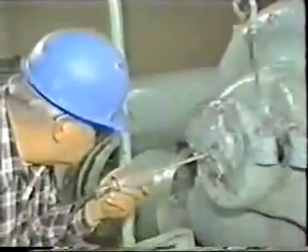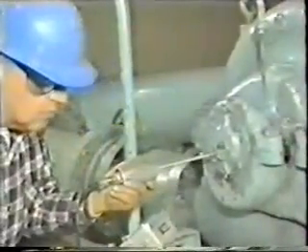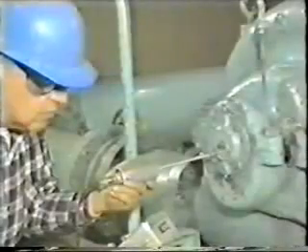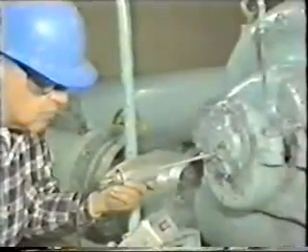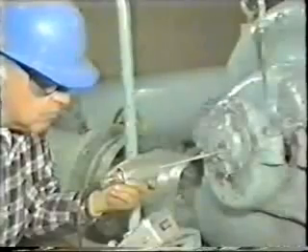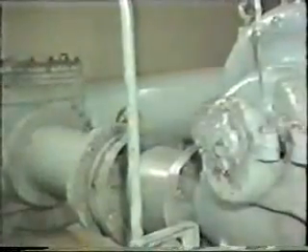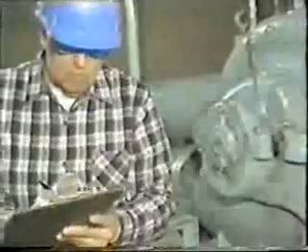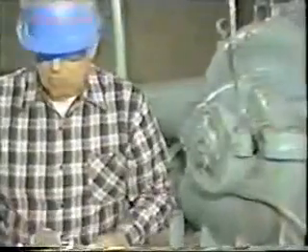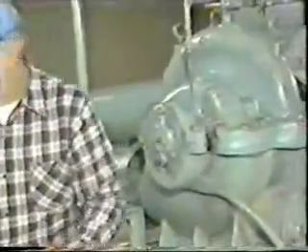When the probe is placed on the end of the shaft or bearing housing, the meter measures axial vibrations. Any excessive vibration readings on this pump could indicate misalignment, so all three of the vibration readings will have to be checked against manufacturer specifications. If vibration is found to be excessive, a detailed vibration analysis may have to be performed.